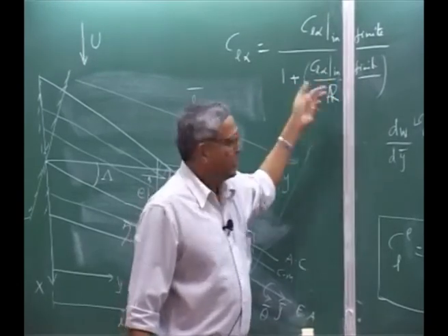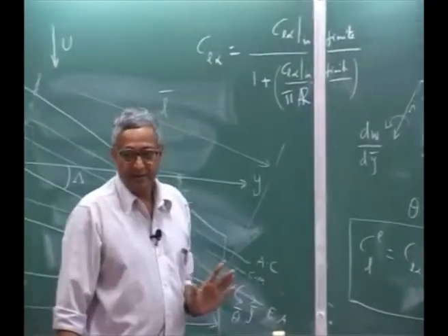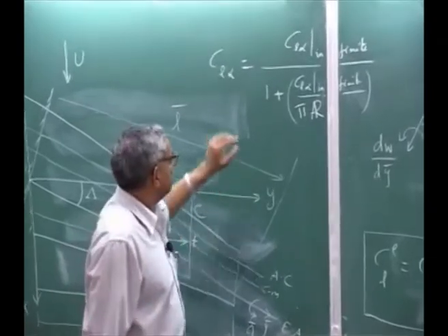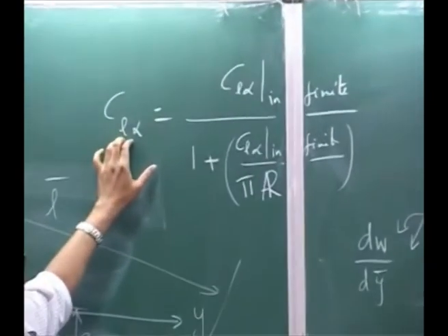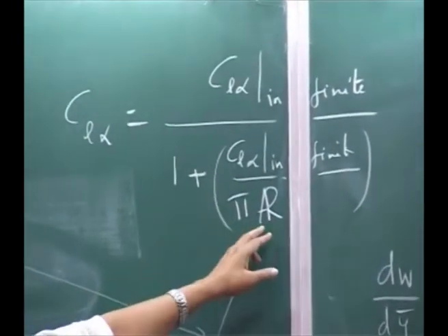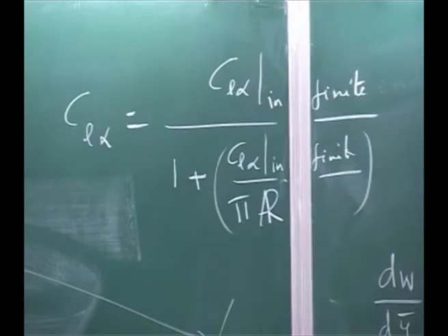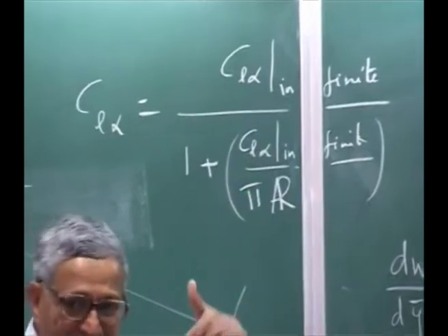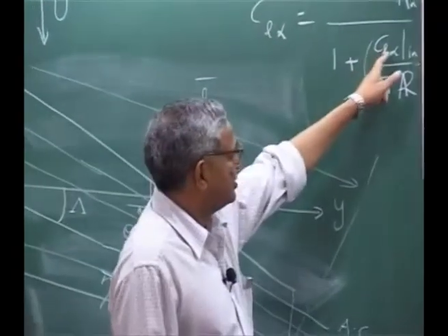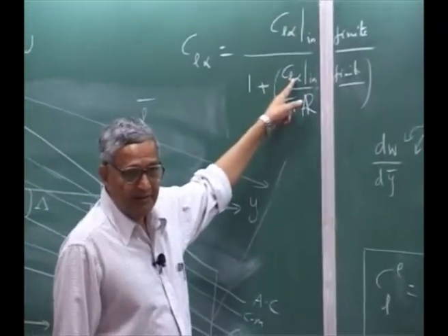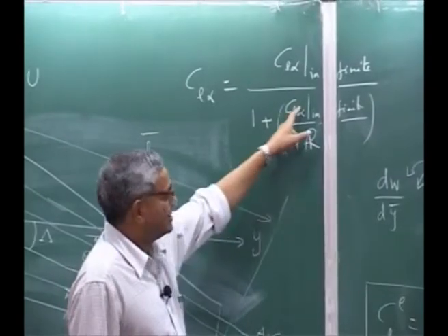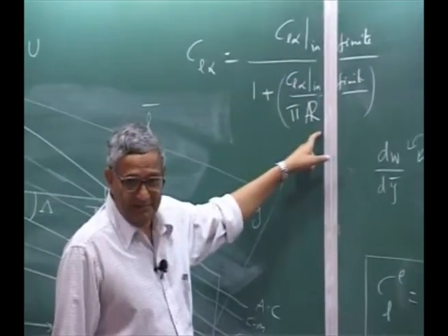So this will only change your C_L alpha for aspect ratio problems. If your aspect ratio is very large, you say that this is lifting line or whatever it may be. Otherwise, if you take 2 pi, this will become pi, and pi will cancel, and 2 over aspect ratio will come.